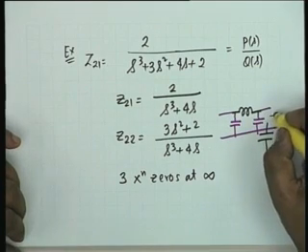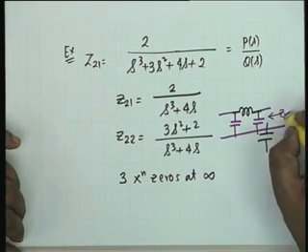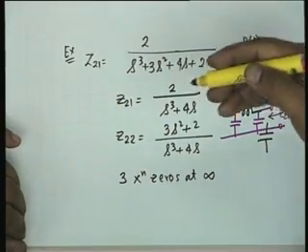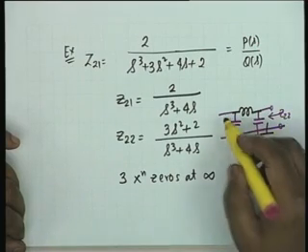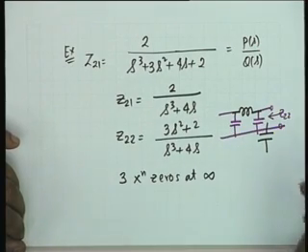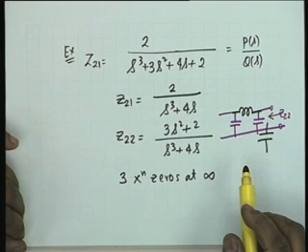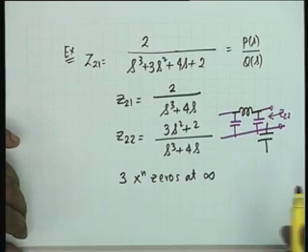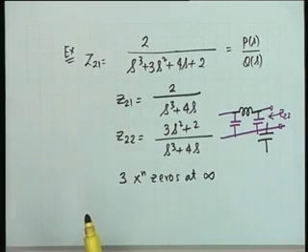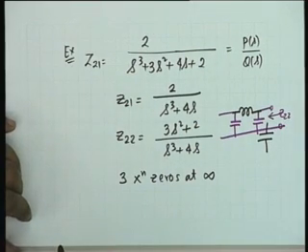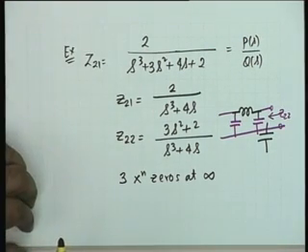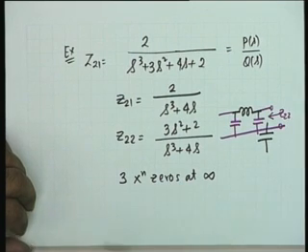And all that you have to realize now is that this impedance, the impedance looking to the right from port number 2, should be equal to Z22 with port number 1 open, and therefore it could have been 3 capacitors in series. 3 capacitors in series is equivalent to 1 capacitor, and therefore they do not realize 3 transmission zeros here, they realize only 1. There must be an isolation between the capacitors.